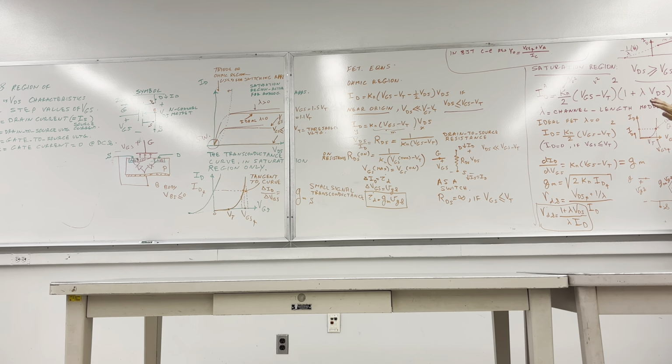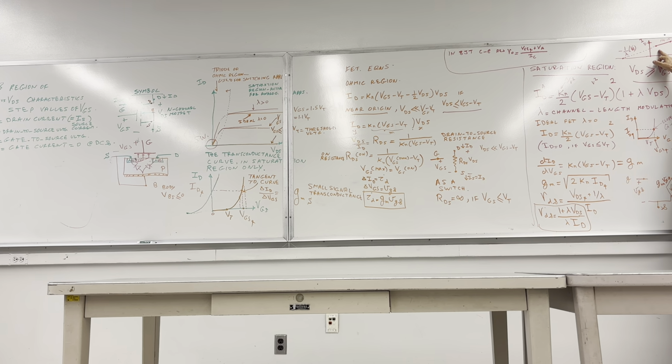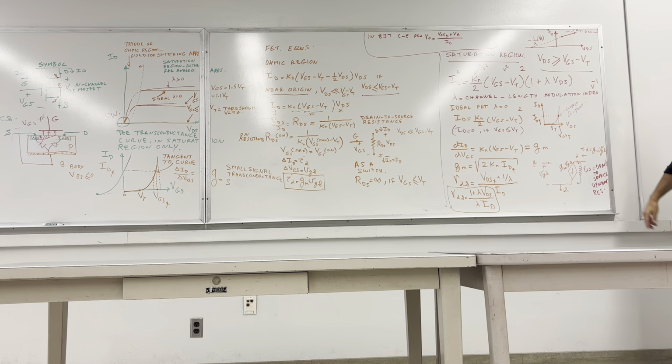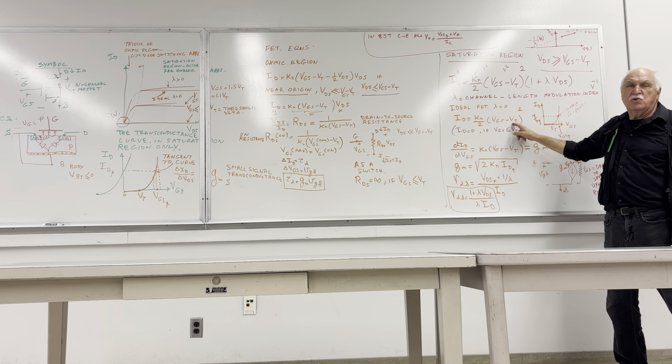But if they depend on it and you know the lambda, by simply taking one of those curves, 2 points on it, extend it, cut it, flip the value of the voltage you see there, that's the value of the lambda. And this equation is going to be mathematically more accurate function. However, in most calculations, they discard lambda, they assume it is 0, and you end up here, parabola. And in this parabola, ID will be 0 whenever VGS is less than or equal to VT.